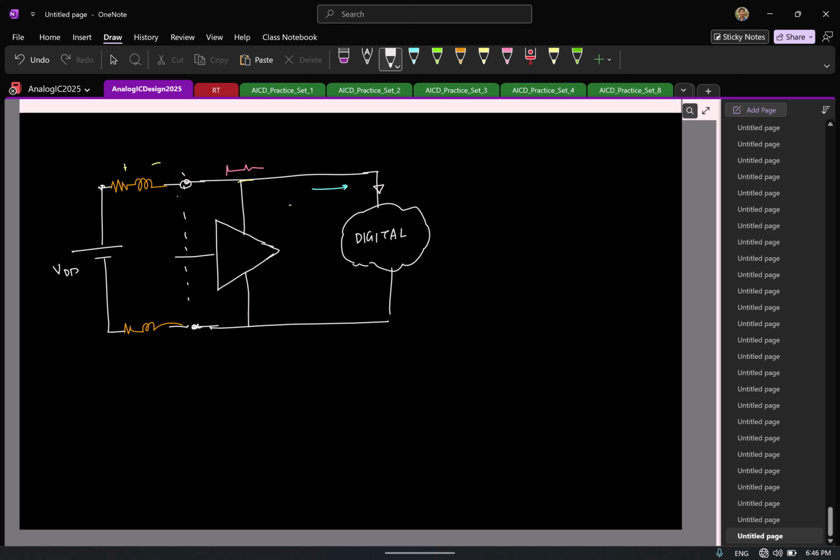See, the actual idea is this: you now have two lines locally to the block, and say that my output is now going to be defined as a potential difference between those two lines. Now the idea is, anytime, let us say, the ground changes. Ground is a reference node, right? If this node changes, this node will also change by the same amount. This will also change by the same amount. Because remember, ground is a reference potential.